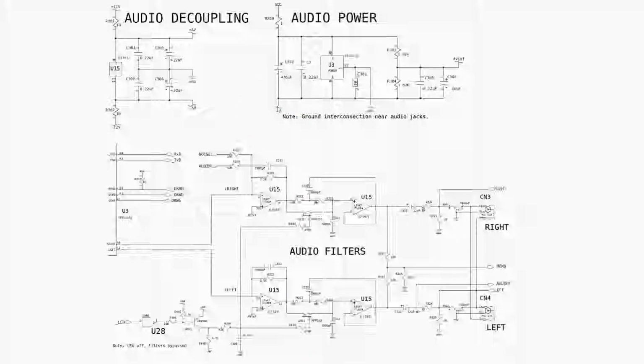It's just done to reduce noise. So I've got switching power supply noise and system noise and all kinds of stuff going on here on these power rails. And what you see here is there's an audio ground reference that's brought out of the Poly chip to this signal. Notice this isn't connected here. There's a ferrite bead that sits between system ground and that audio ground reference to block all of the switching power supply noises and other noise from getting through. So it's blocking essentially RF kind of noise. So it'll make the audio section a little bit quieter.